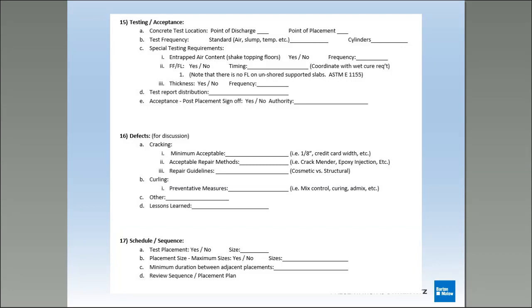And then, getting into the schedule and sequence: test placement, test placement, test placement. Always do a test placement with a test grind on it. Make sure everybody buys into it before you jump into a big slab and everybody's upset. Get all the bugs worked out early, and you'll be on the road to success there.